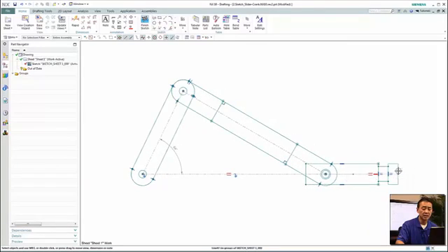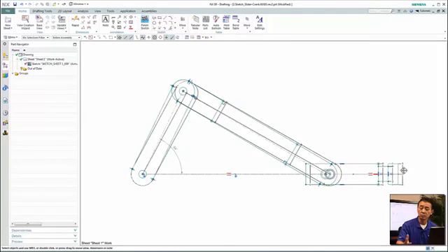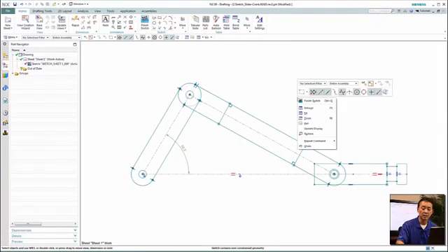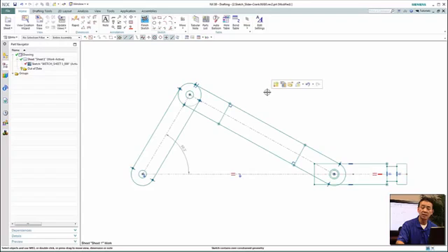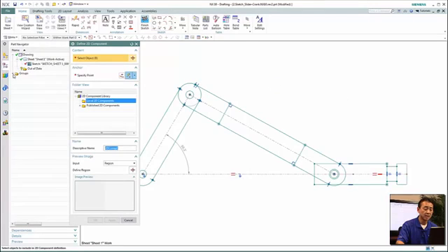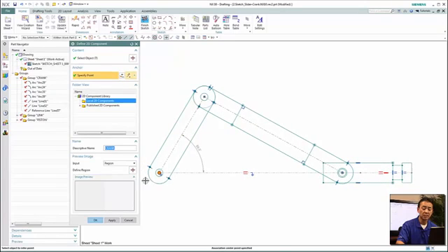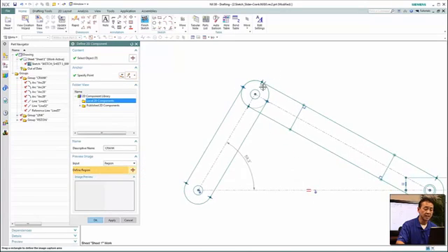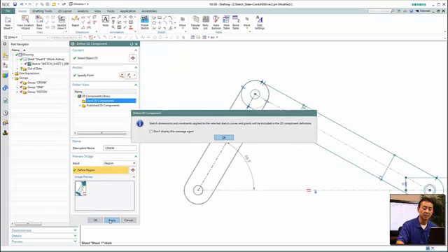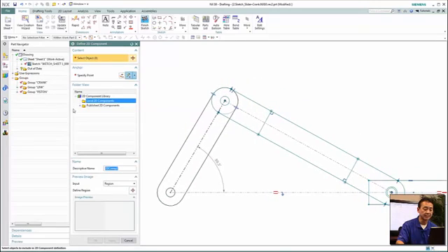What we have already done is precondition this by applying assembly constraints and applying a group within this particular sketch. And then these individual geometries are already defined. Now what we want to do is define the 2D component for the NX layout. By grabbing each one of these individual geometries within that particular group, we can quickly define the information of that.